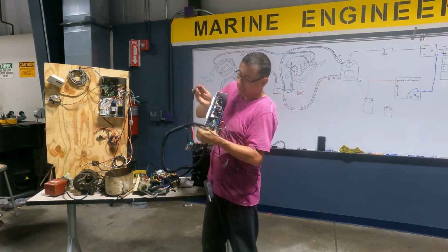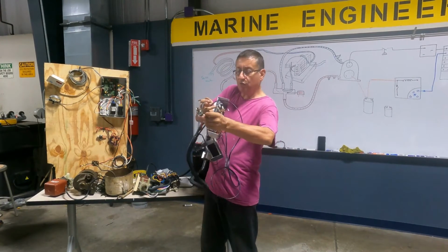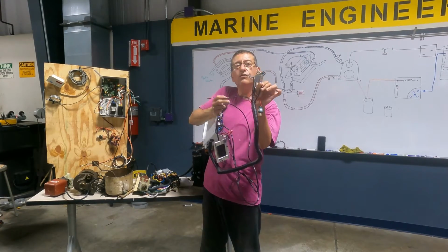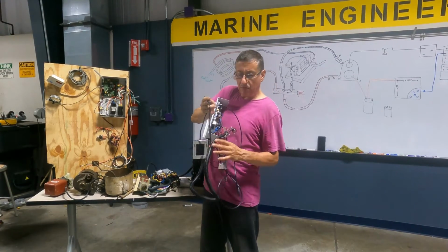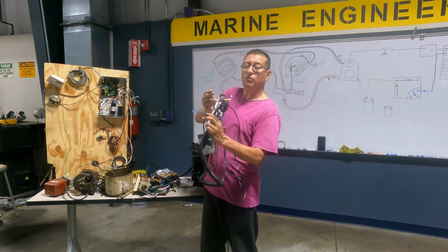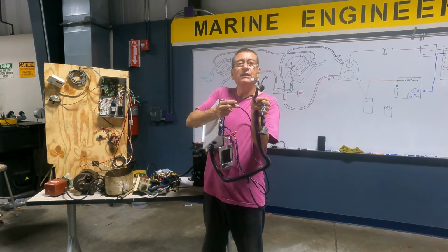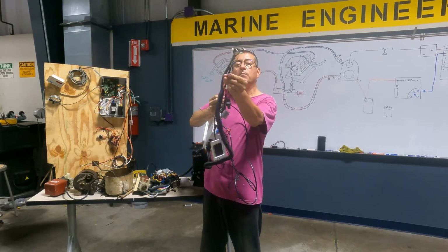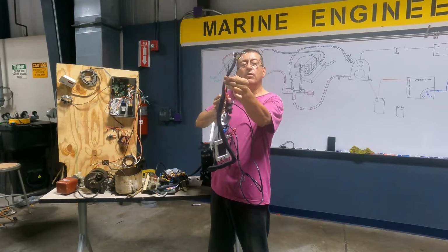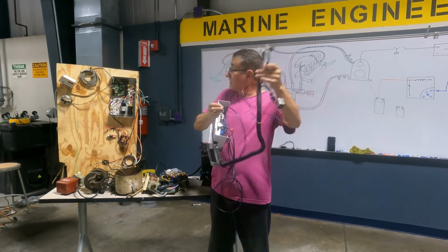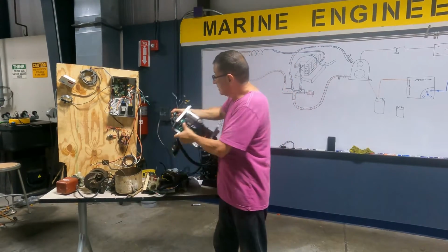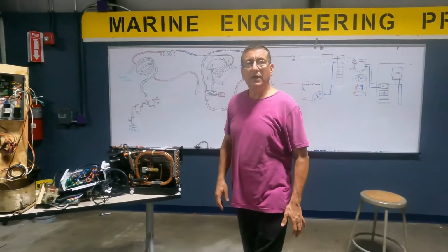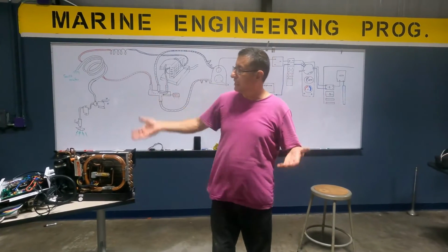You have the pressure switch. You have the solenoid for the Y valve. You have the thermal contactor on the compressor, and the three cables for the relay of the compressor, and you have the power for the blower. You see, the power for the blower. Exactly the same here. We are going to analyze this one and this one. You need to be familiarized with both harnesses.